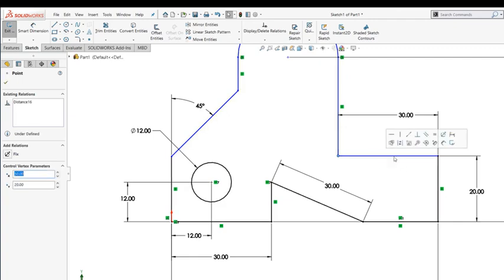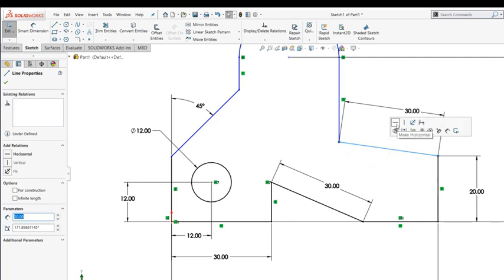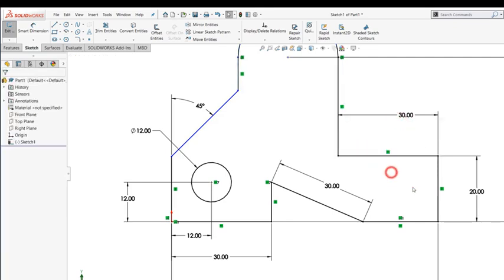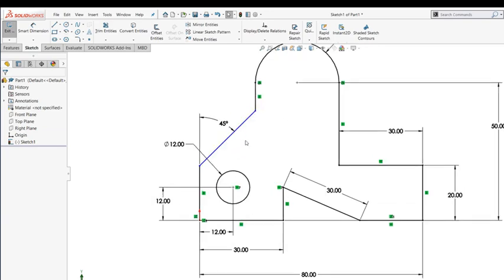So it looked like it was horizontal, but it's not actually horizontal. That can only be found by dragging these endpoints. So it shouldn't move in a tilted way. So just click on it, add a horizontal constraint there. And what's left is only this line.